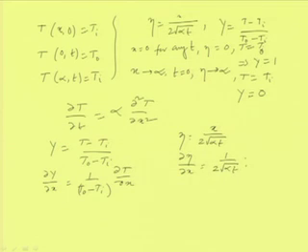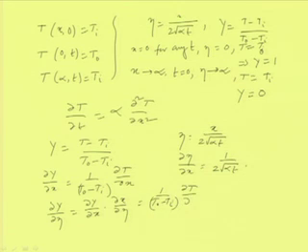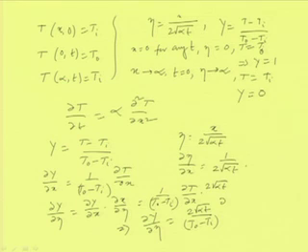Then again, we need to get ∂y/∂η, not in terms of x. So, ∂y/∂η = ∂y/∂x × ∂x/∂η, which gives 1/(To − Ti) × ∂T/∂x × ∂x/∂η, where ∂x/∂η is the reciprocal of this, that is 2√(αt). This implies that ∂y/∂η = 2√(αt)/(To − Ti) × ∂T/∂x.